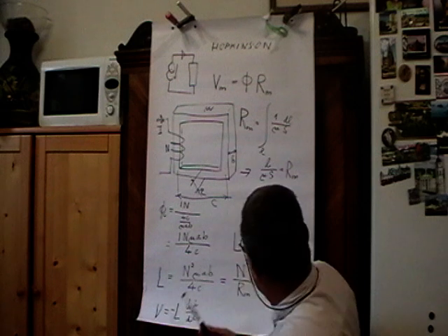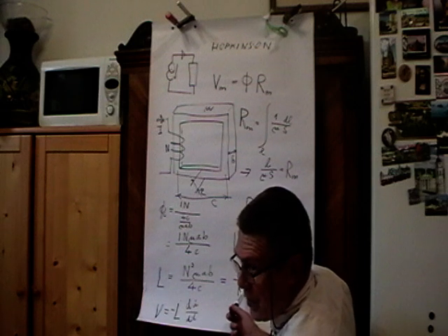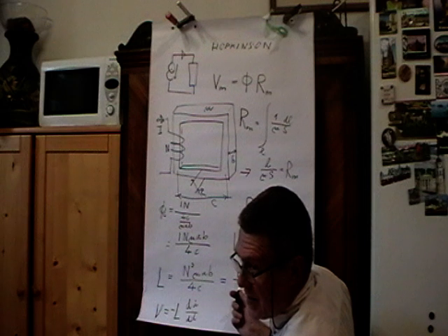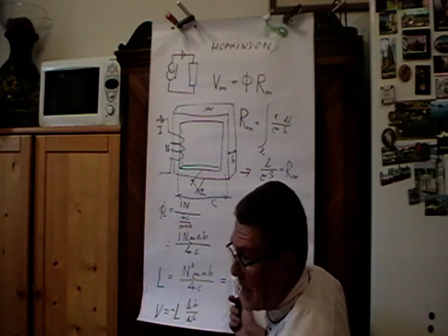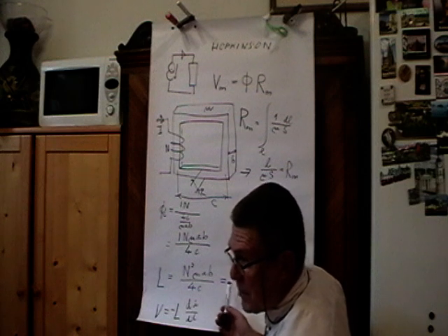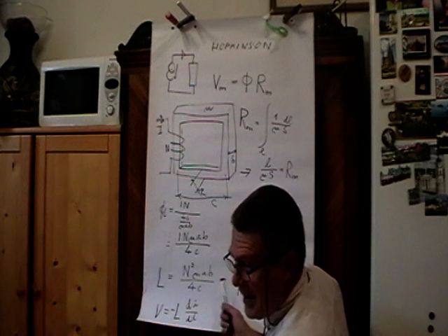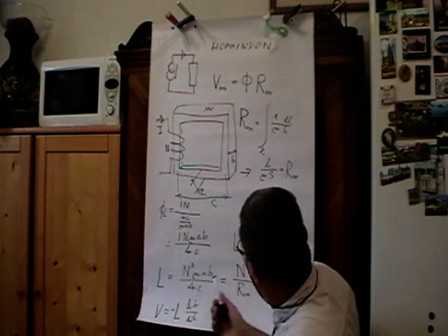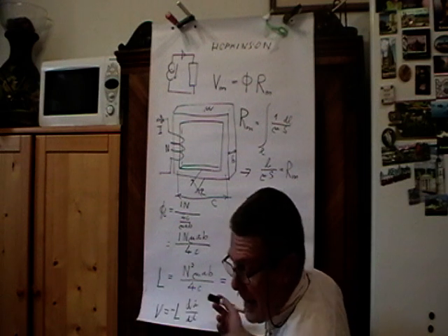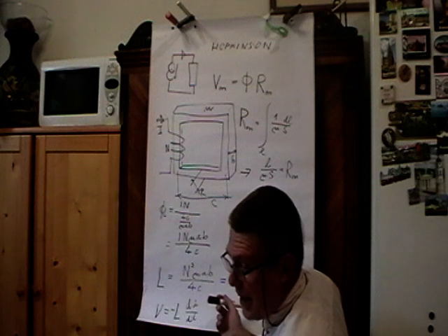And we found that the inductance depends quadratically on the number of turns. If you double the number of turns, you double the magnetic flux in the core, and it counts 2 times in the doubled inductor, so the total flux in the inductor gets 4 times bigger.